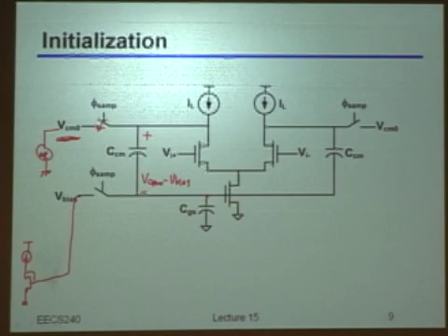So I will need a certain way to sink any possible variation in the common mode and in common mode current that there are. So let's assume indeed that there is a variation, some extra, even small, jump in the common mode current on both sides. So what am I doing there? If I am in that condition, as soon as these switches get closed, this voltage source needs to basically sink your current.